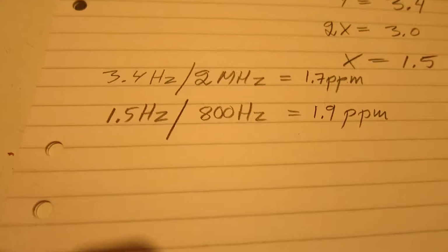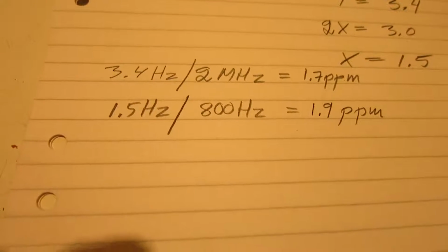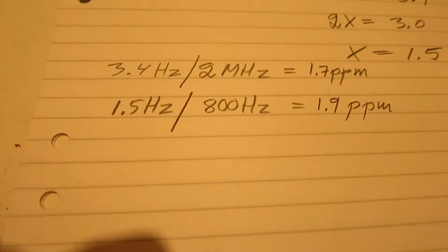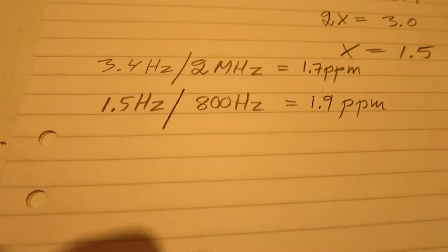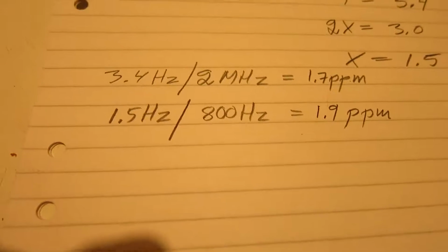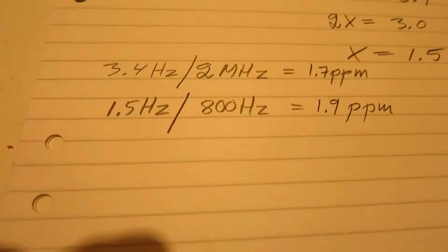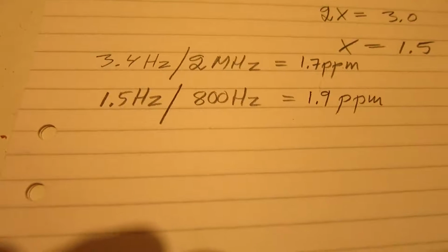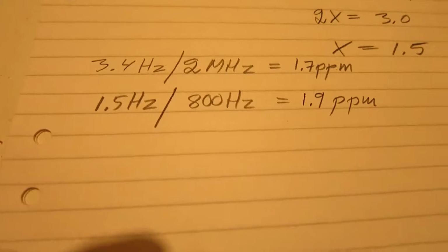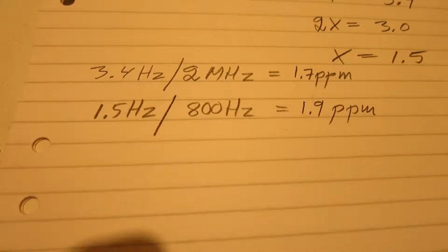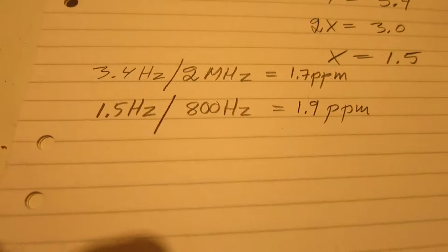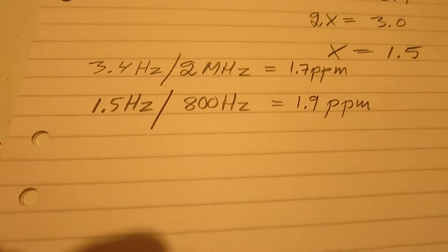Now the precision in my measurement isn't very high, so I would say that this Perseus unit has an error of 1.8 ppm. If I had calibrated my Perseus, the center frequency would probably have been correct, and then only the baseband sampling rate would have been wrong.